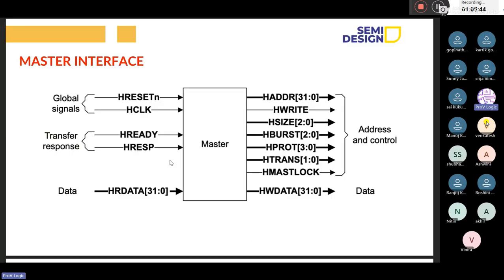Then what about the burst length? We have burst lengths like wrap 16, wrap 32, wrap 64. Based on that, it will differentiate the number of bits or number of incrementing bits. In the same way, only the burst and size will change, the remaining are all the same. HTRANS will be the same. And what else will change?